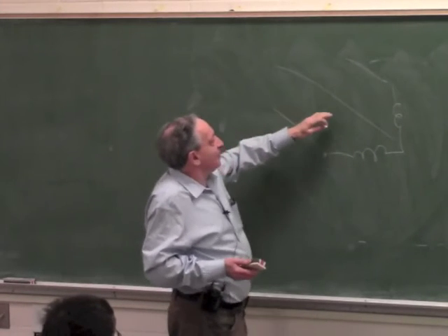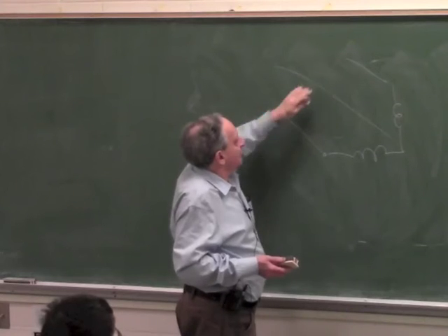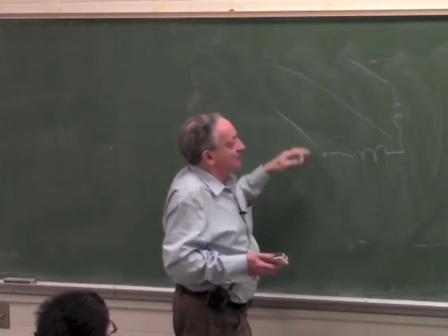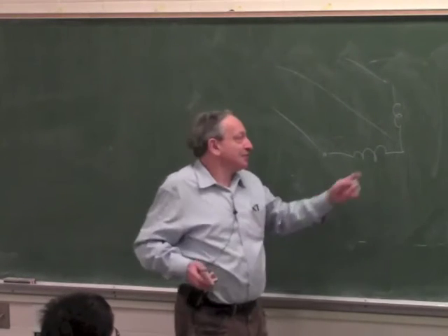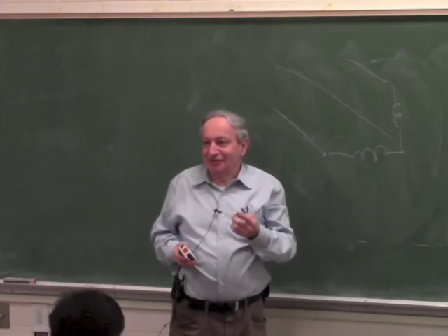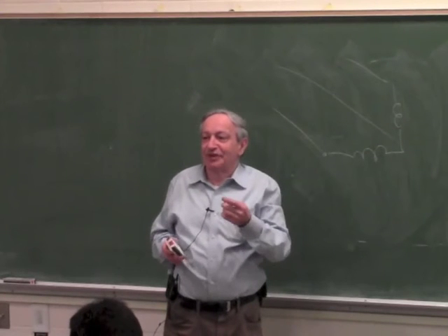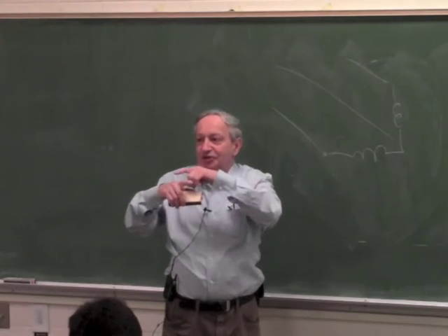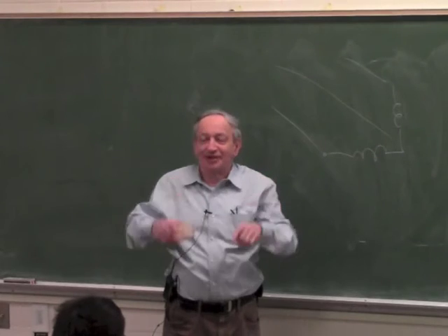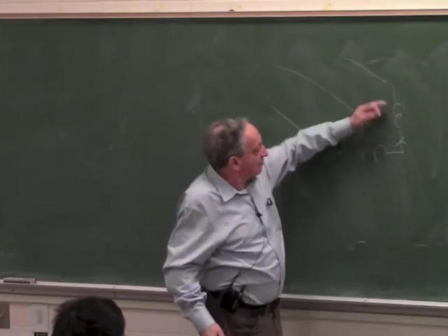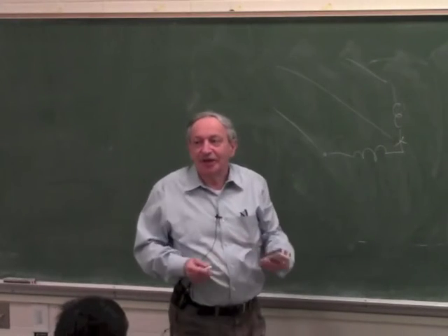If you switch both of those, nothing happens, because you have to switch one to reverse the field, right? Sine and cosine is one direction, so you have to have sine and minus cosine. So what you have to do is disconnect and flip the coil. I went through it. Okay.